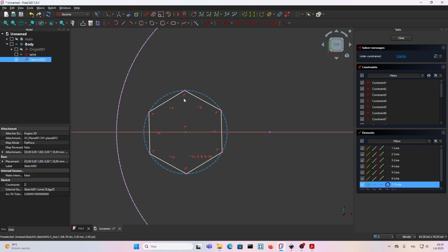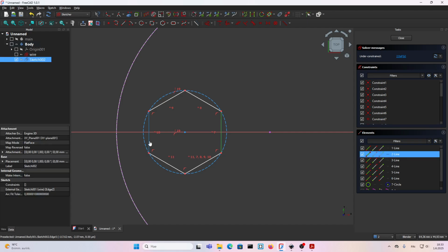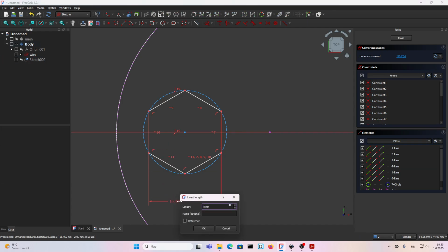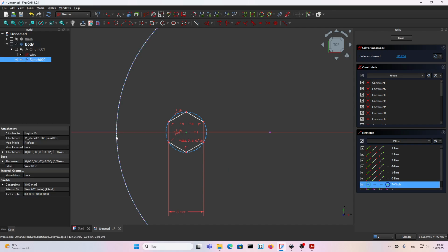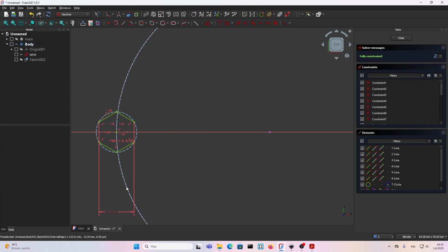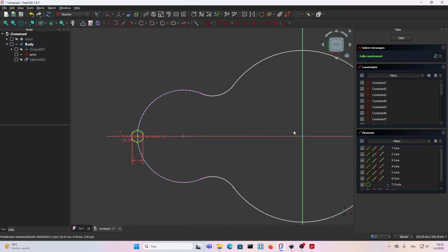Click on this dot and this dot and make them linear from here. Now they are linear. The size, choose these two, D from the keyboard. We said 8 millimeters. The position, click on this dot, click on this external geometry, C from the keyboard. Now it's positioned correctly.